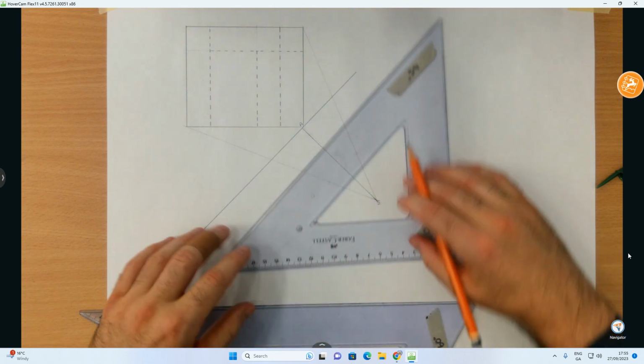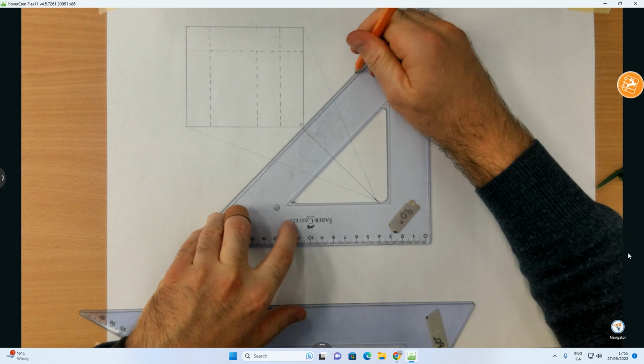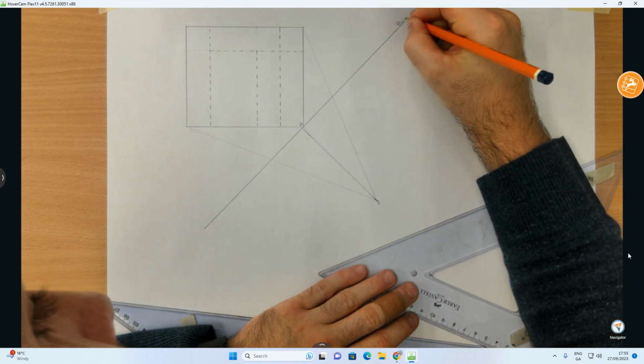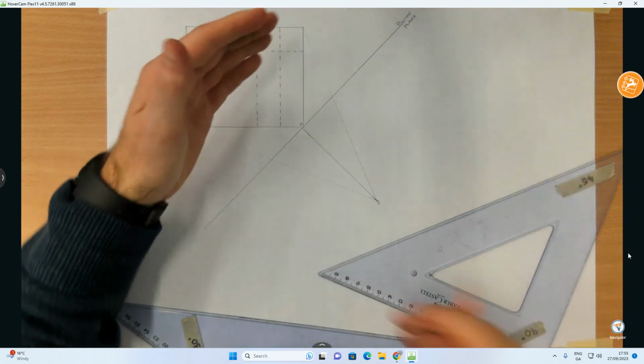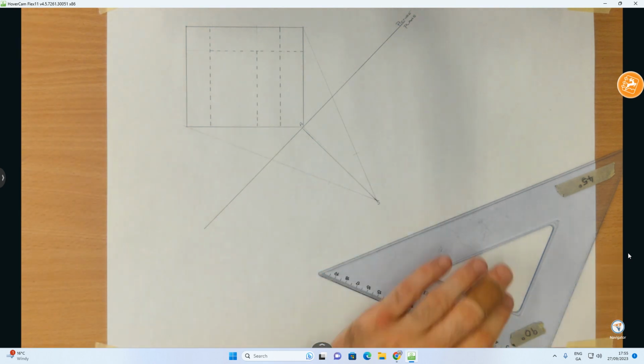And what I'm drawing here now that I have that, I can extend it on. That there is my picture plane. So essentially, everything that we see from this object is projected onto the picture plane, but we'll draw the 3D of it down here, the perspective view.